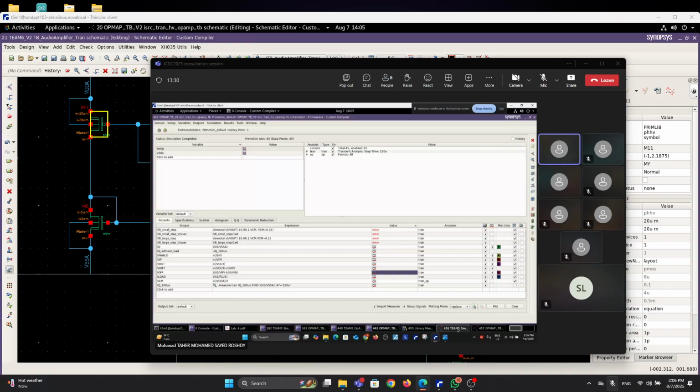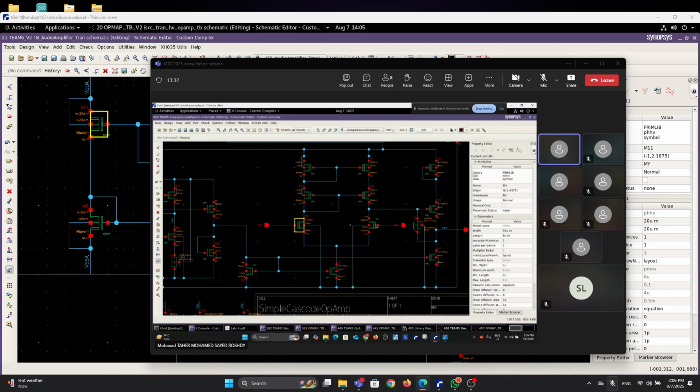Regarding the common mode noise, I would assume the main problem can lie in the differential MOSFETs here, right? I mean, I would say these two MOSFETs, the M3 and the M0. If we maybe modify the width of these two MOSFETs, it could maybe fix the problem with the common mode error, like you said. Is it?